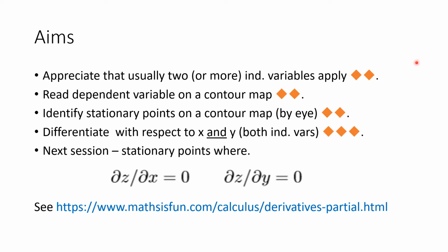But copper may well have alloying elements, and those will increase its electrical resistance, but also increase its lifetime. So both have an impact on the cost of operating our generating system, our transmission system, and therefore that cost should be optimized not only with respect to the wire diameter, but also the weight percentage of alloying element.